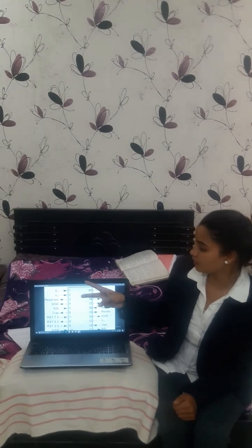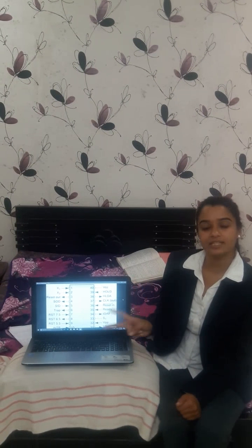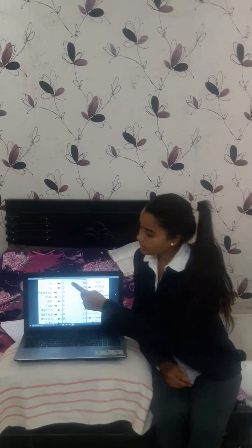You can see that the first two pins are X1 and X2. These are called the crystal connection pins. The 8085 contains an oscillator on chip. This oscillator is connected between these two pins, X1 and X2. It provides the necessary signal to the peripheral and the processor.